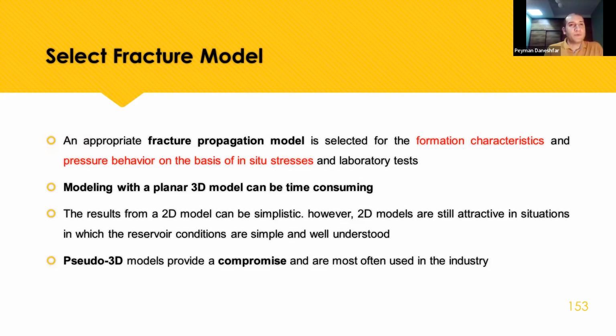Every time your procedure and schedule are okay, but the software will show you about a 100-meter fracture length, but it's not okay. It's just the optimum shape of the fracture, nothing more.